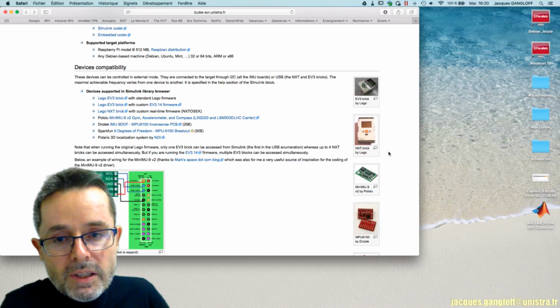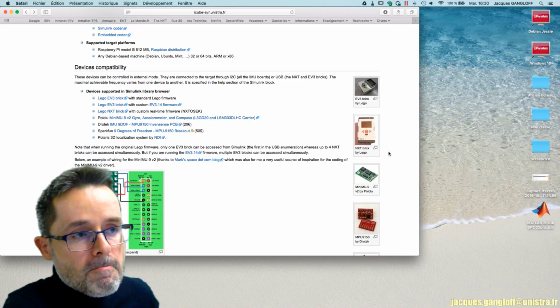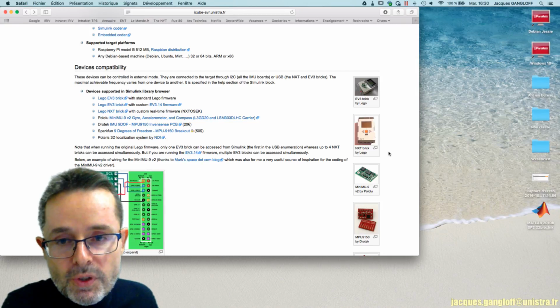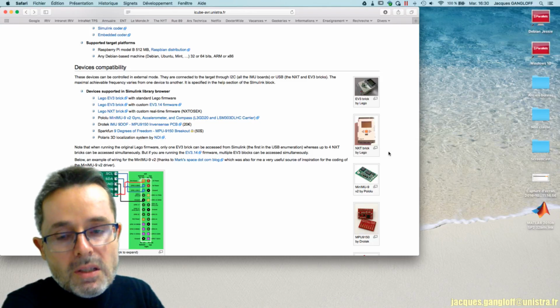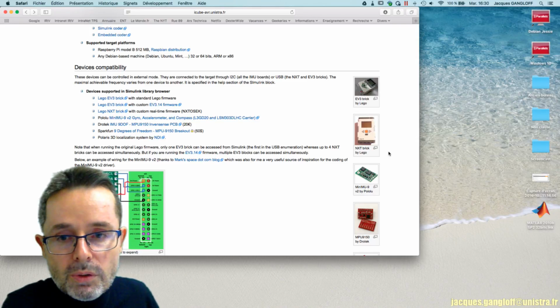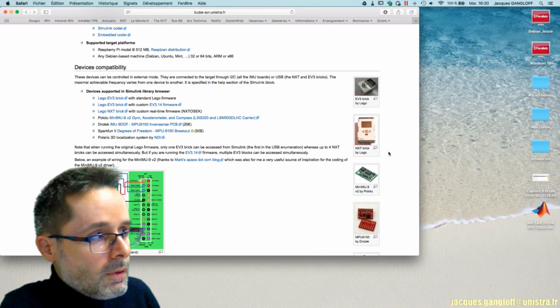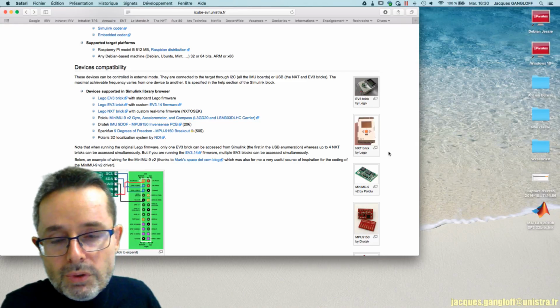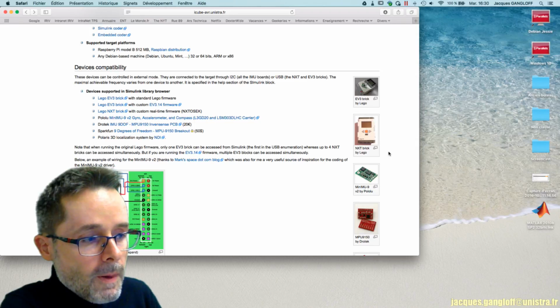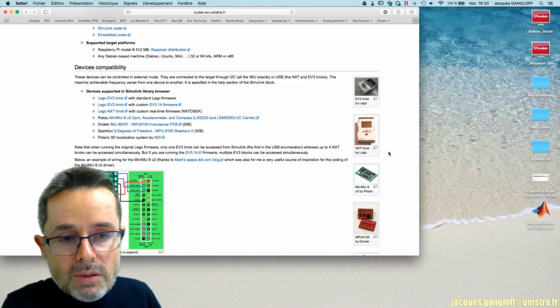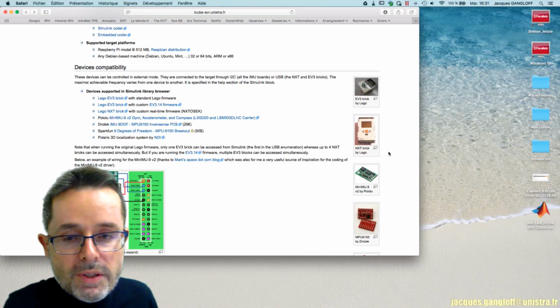You have a PC running time-consuming image processing, connected to a camera, which in this example was a high-speed camera running at 500 Hertz. You can poll this PC through the socket to ask for the new values of, for example, some feature in the image, and you can use it as visual feedback for visual servoing.